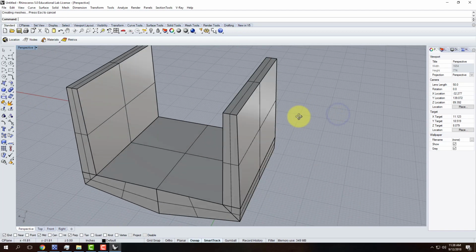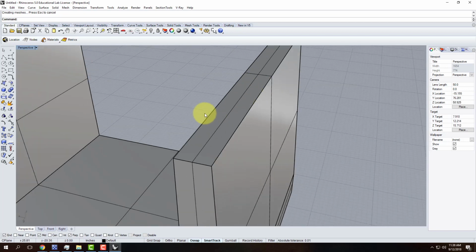And if this were a concrete bridge, these sharp corners would have a tendency in practice to chip, or when you pulled the forms off, they would tend to break at the corners. So typically what's done on concrete, and a perfect example of it is the little planter that's sitting right outside here. You probably never paid any attention to it, but you're going to learn something new right now. The edges of that concrete have little angles on them that are called chamfers. They're there because of this same problem. If you did it straight, it would have a tendency to chip on the corners, or when you pulled the formwork off, it would chip then and it would look ugly.